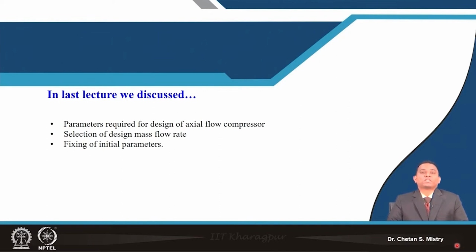We also discussed that for supersonic engine design for military applications, the middle stages may also go transonic, because there we have no concern about fuel economy.